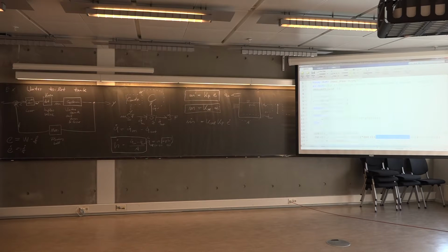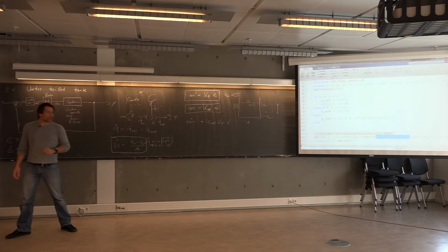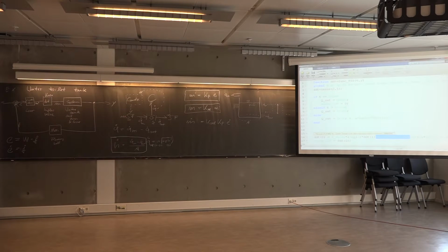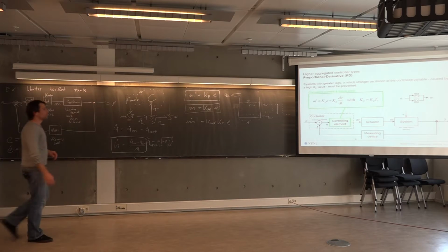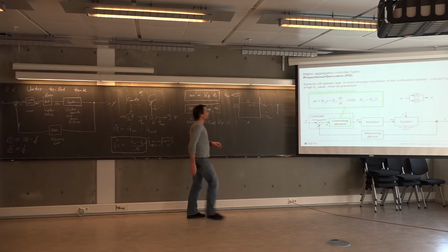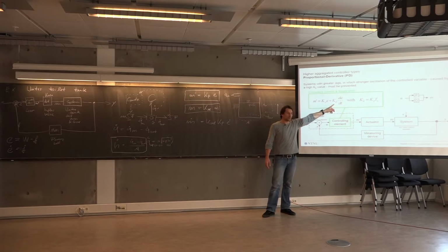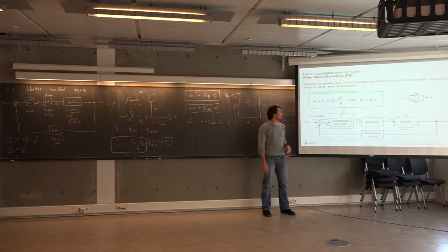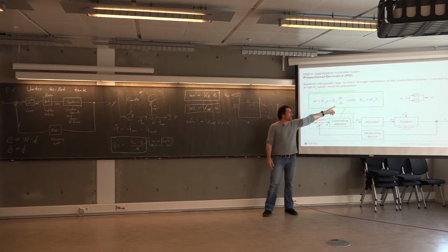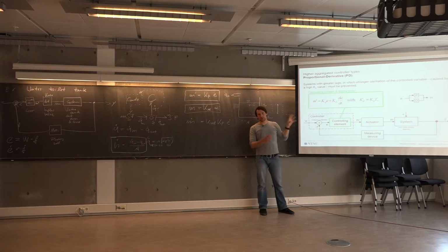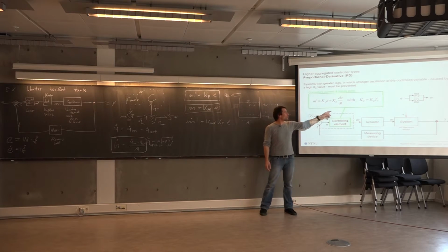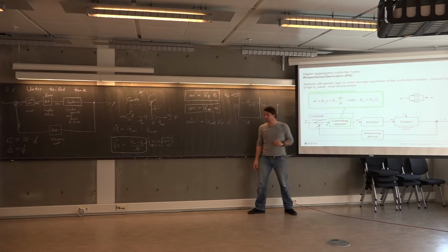And if we do that, we will actually end up with a second order derivative for this term here, right? This is the derivative control action. It's the rate of change of the error. Since we are using the derivative of this equation in the function file, because we want to solve that over time, we will end up with the second derivative of the error.